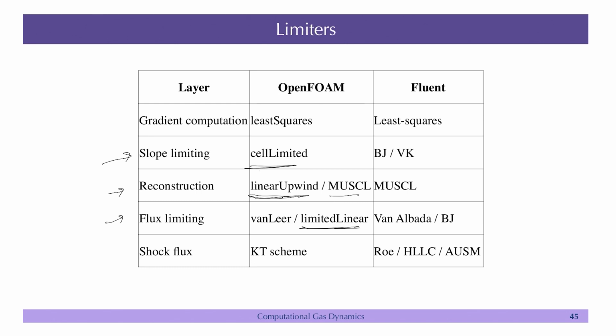If you have shocks at very high Mach number, then the normal pressure based schemes that we discussed earlier may not work. The only flux based scheme you have in OpenFOAM is the Kurganov Tadmor scheme, which is basically an upwind based central differencing scheme. Central differencing by itself is not stable, so there is some upwind bias. That is the only scheme that we have, but of course, there are new user based implementations coming up in terms of HLLC.